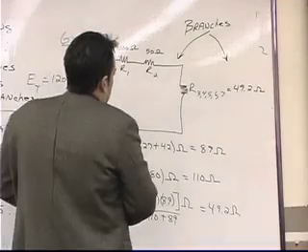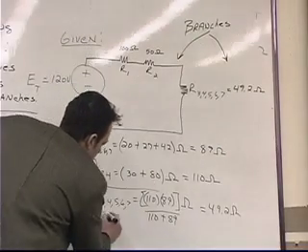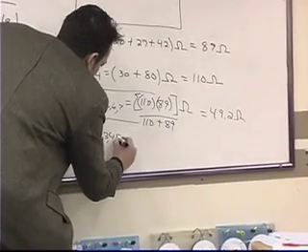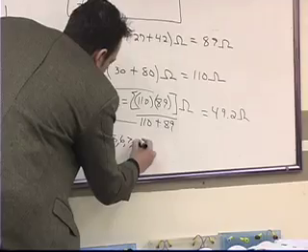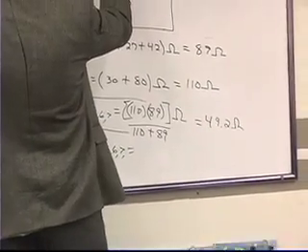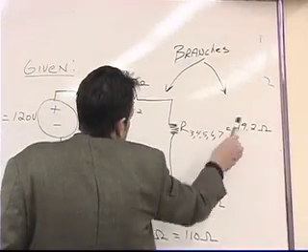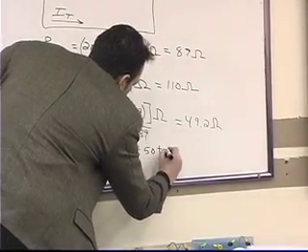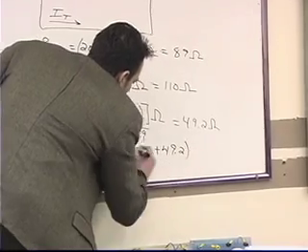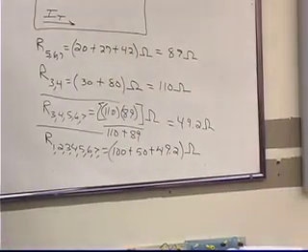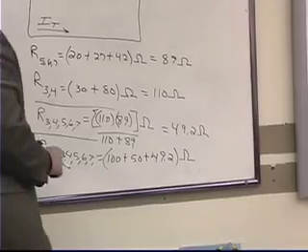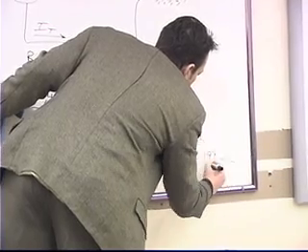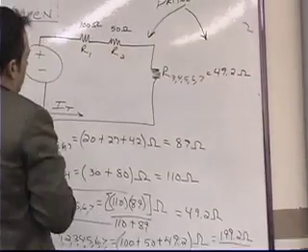Okay? And so if we combine those resistors, then we're going to have R1,2,3,4,5,6,7, and that's going to be equal to 150 plus 49.2. What's that? 100 plus 50 plus 49.2 ohms. And what is that? 199.2. So that's the total opposition to current flow for the circuit.